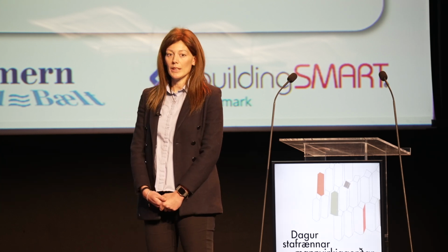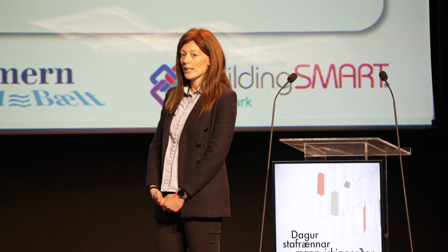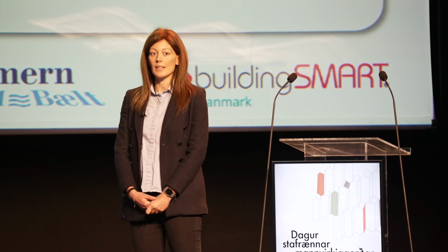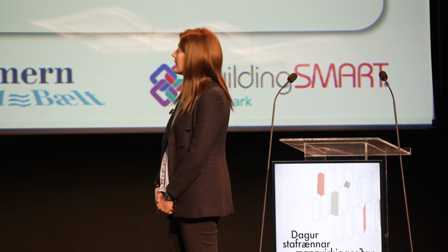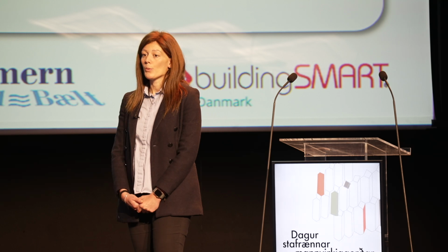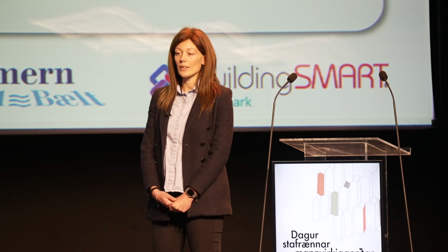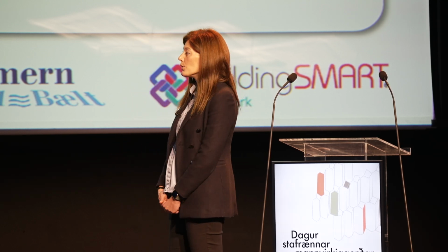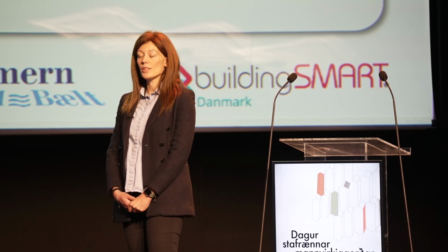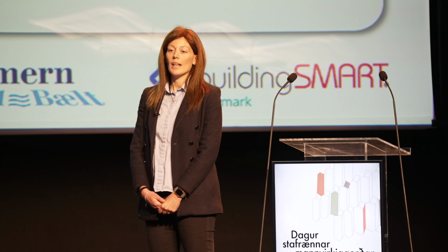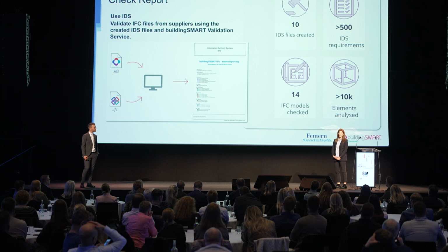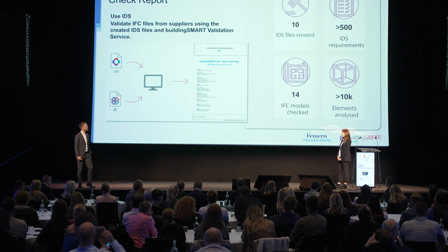Of course, during the design phase, we are checking our model, but it's hard to check all the geometry and the properties in the model itself. So in this case, IDS will help us in this task as well. And we will give back to our contractor the export of the issues that we got in the models, and possibly the BCF, so that they could use the open standard format of the BCF to fix the issues within their model.